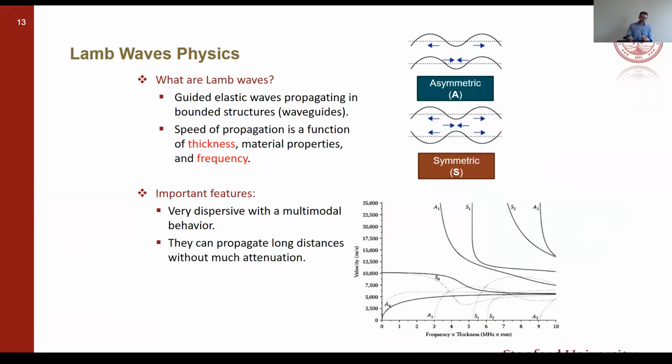We do it through the so-called sound waves, or the guided waves inside of slabs, which are waves that propagate in a very thin slab of material. They are advantageous because they can be very sensitive to interaction with the medium on the top and the medium on the bottom. And they don't have as much attenuation as the bulk waves. They are used in industry, especially in non-destructive testing, for evaluating the samples and components of a mechanical system.